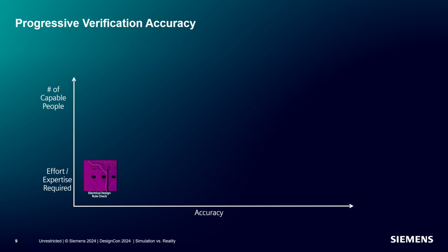And it starts with electrical design rule checks. This is exactly what it sounds like. It's sort of a visual check to ensure that your design process fundamentally followed the rules in place. It's essentially an instantaneous process that you could conceivably just do by looking visually for common problems if you have enough time. The computer can do it, like I said, almost instantly. Is my spacing correct? Are my widths correct? Things like that. This is tasked to sort out all the blaring issues.